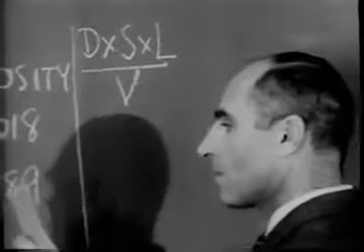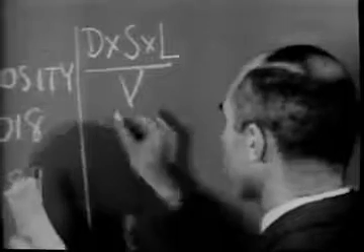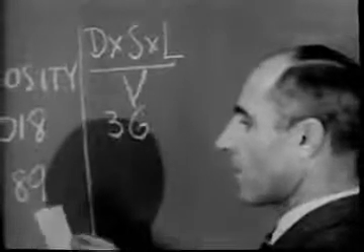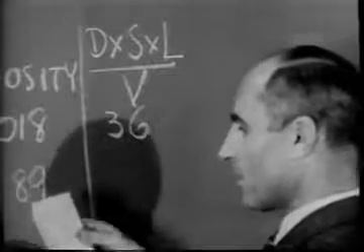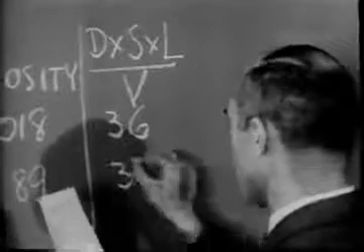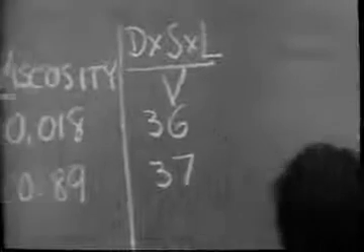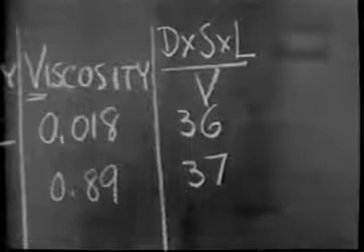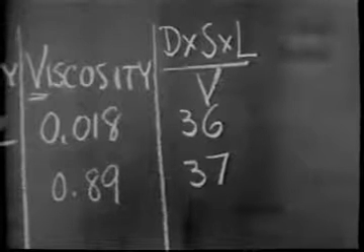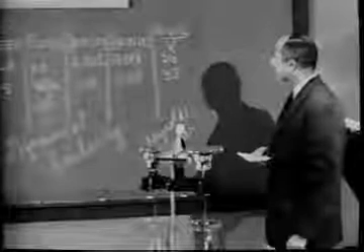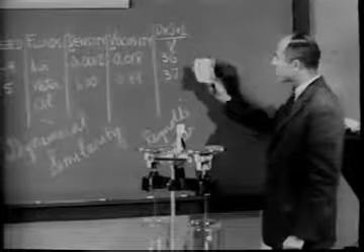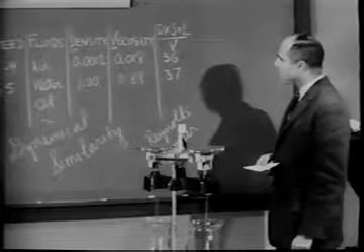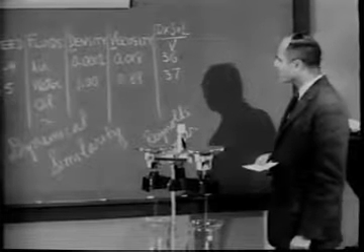You can see that for the experiments we selected, the Reynolds numbers differed by only a few percent. So while these two experiments, one in a gas, one in a liquid, appear very different to the eye, they are empirically similar. And as you will see later, from a measurement of the drag of the plastic ball in water, this similarity enables us to predict the drag of the helium balloon in air.